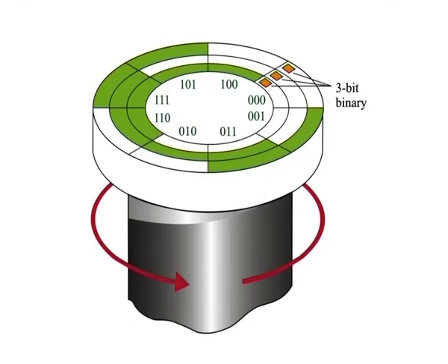For example, let us again consider what happens when the brushes are on the 111 sector and about to move into the next sector, 101. The only two possible outputs during the transition are 111 and 101, no matter how the brushes are aligned. A similar situation occurs at the transition between each of the other sectors.